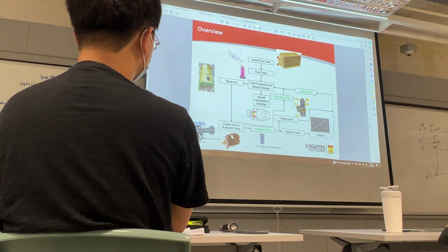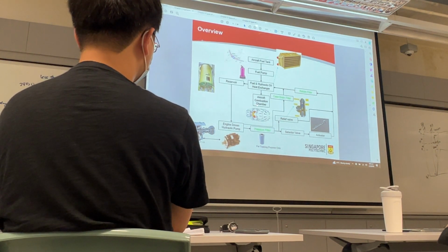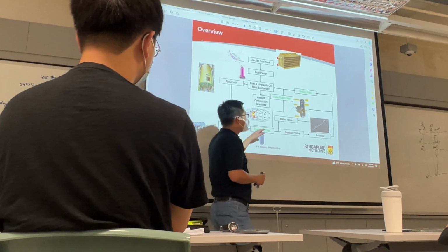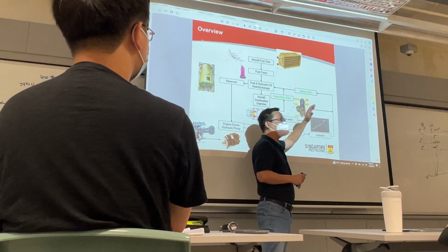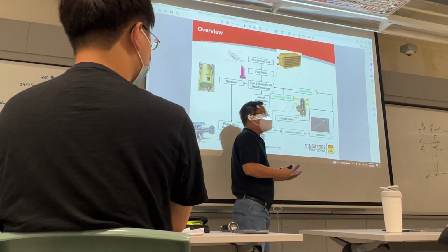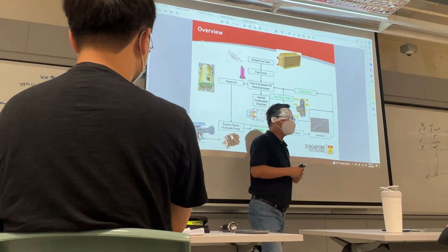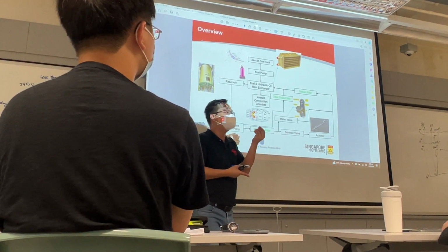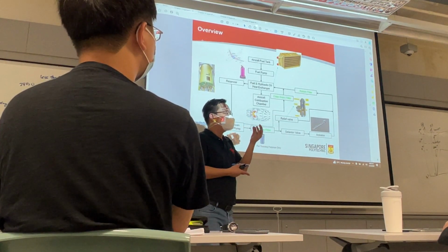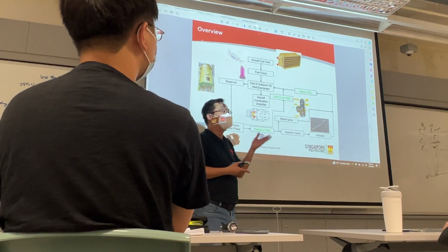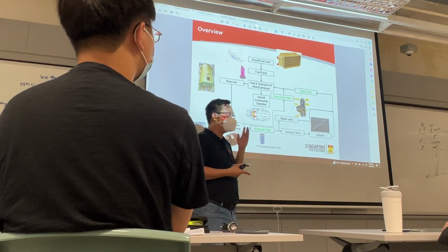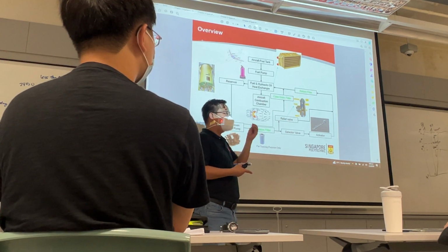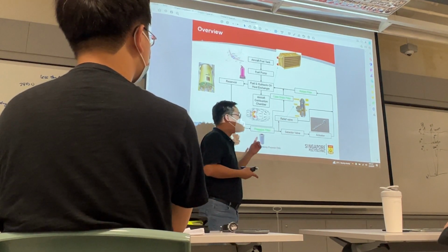After cooling, it must go back through the case drain filter because it goes back to the reservoir. Now the scary thing is, when I have to change these filters based on the book requirement, we will always want to open this one first. You know why? When you open this one and look inside, you see a lot of silver debris, shavings. How does it look? It's a bit like what ladies put on their face as glittering powder. It's the same thing, but I never use it and rub it on my skin, that's for sure. But when you see this, what does that mean? Where does it come from?